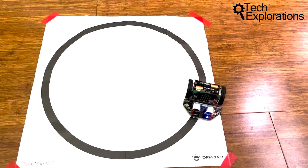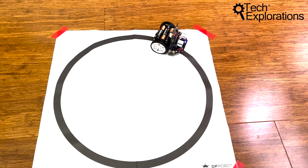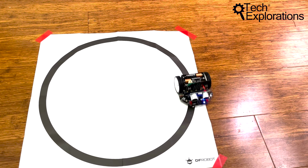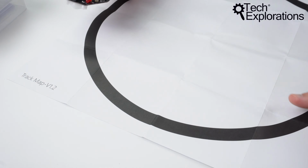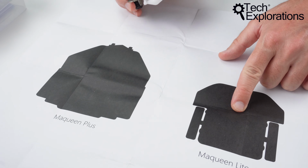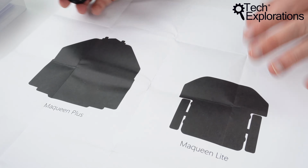Now if you're having trouble with this experiment and your Maqueen is unable to follow the line reliably, there may be a problem with the calibration of the line sensors. The line sensors come pre-calibrated from the factory, so it should actually just work, but you never know. So what you're going to need is the calibration printout that is on the opposite side of the line sample piece of paper. So just flip it over and you'll see that there are two areas for calibration. One is for the Maqueen Lite, which is the device that I'm using here, and the other one is Maqueen Plus. So you could use either one.